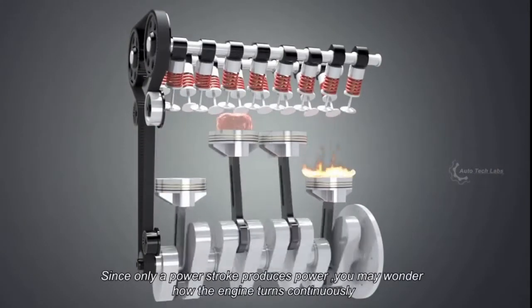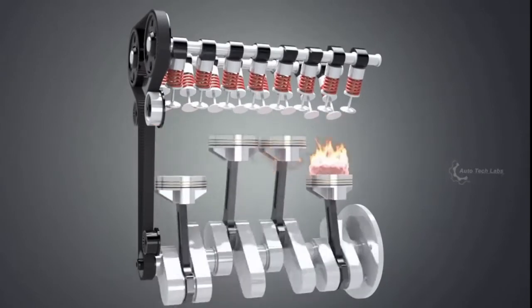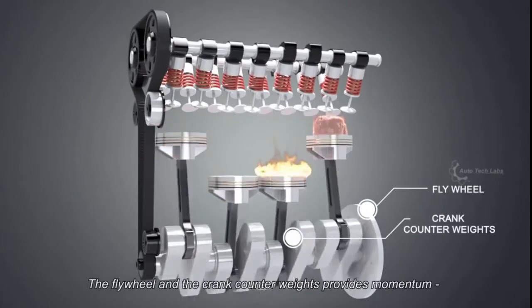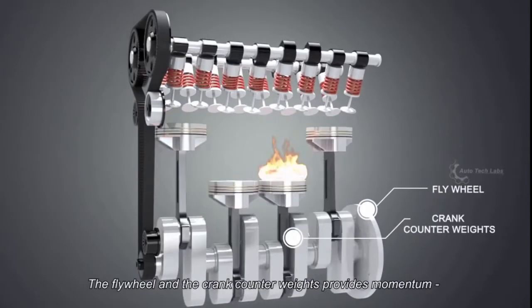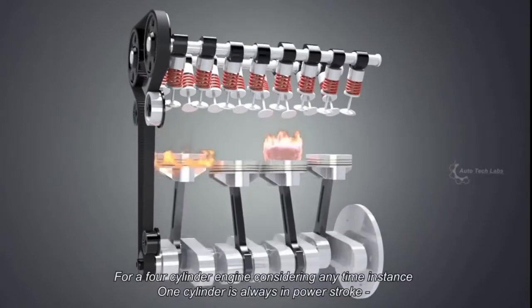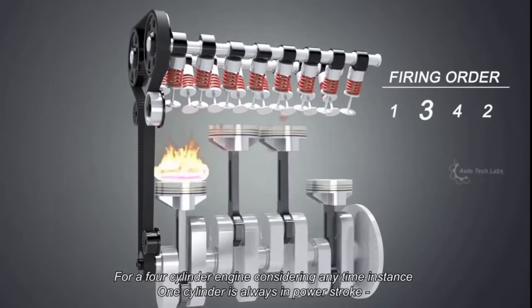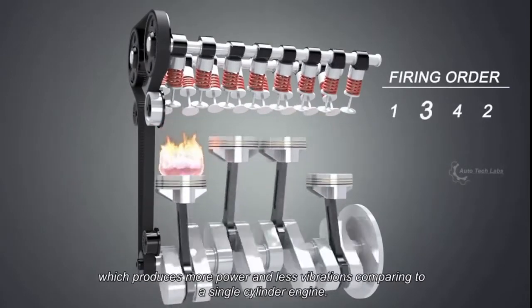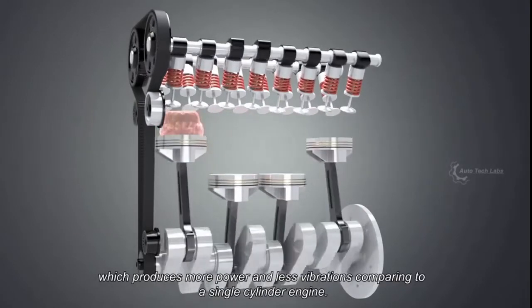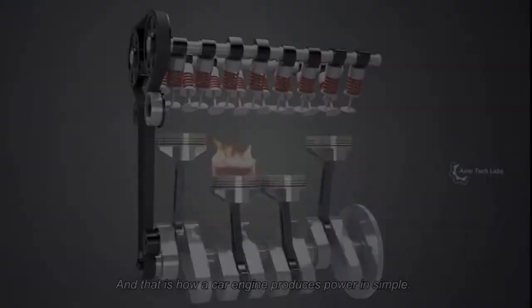Since only a power stroke produces power, you may wonder how the engine turns continuously. Well, the answer is in the crank itself. The flywheel and the crank counterweights provide momentum, which keeps the crankshaft from stopping immediately. For a 4-cylinder engine, considering any time instance, one cylinder is always in power stroke, which produces more power and less vibration compared to a single-cylinder engine. And that is how a car engine produces power in simple terms.